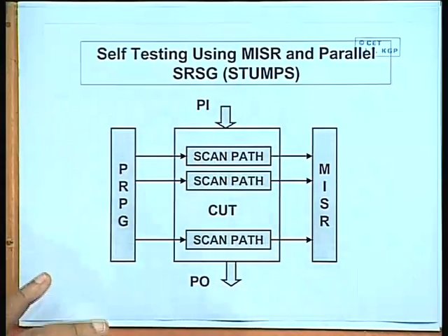This method also has been found to work pretty well, because before just adapting any such method in actual practice, you will have to find out or evaluate through simulation how good or how bad this method is, and what are the implications of using it. You will have to evaluate the fault coverage through simulation a priori, of course, before actually implementing a BIST scheme. Okay.